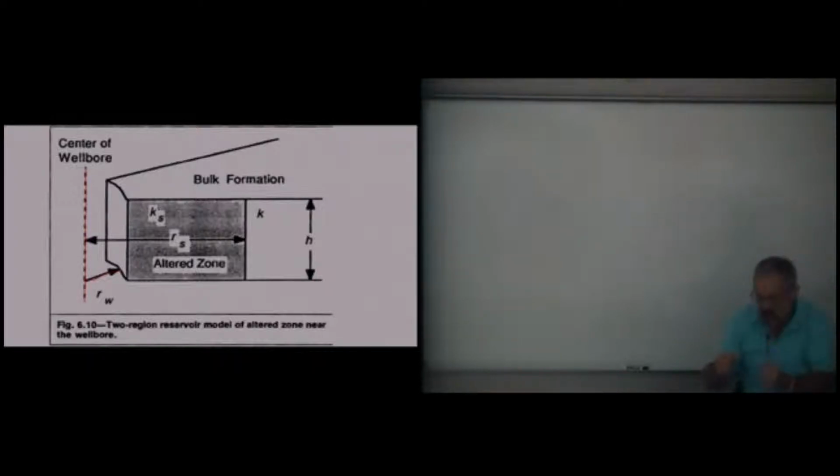If I lower a pressure bomb, the gauge gives you a Pwf, the pressure of the well flowing. It extends out to the wall of that casing, which is the inside diameter of the casing. How do we find the inside diameter of the casing from the nominal diameter and the weight and the grade?